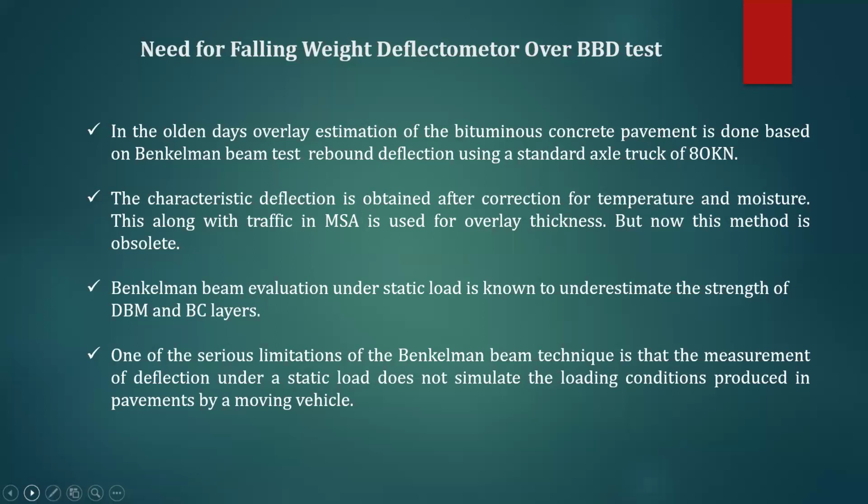This is used along with the traffic in MSA for overlay thickness design. But this method is now obsolete. What is the reason for not using this? Basically, the Benkelman beam evaluation test uses a static load. Basically, it underestimates the strength of the DBM and BC layers.